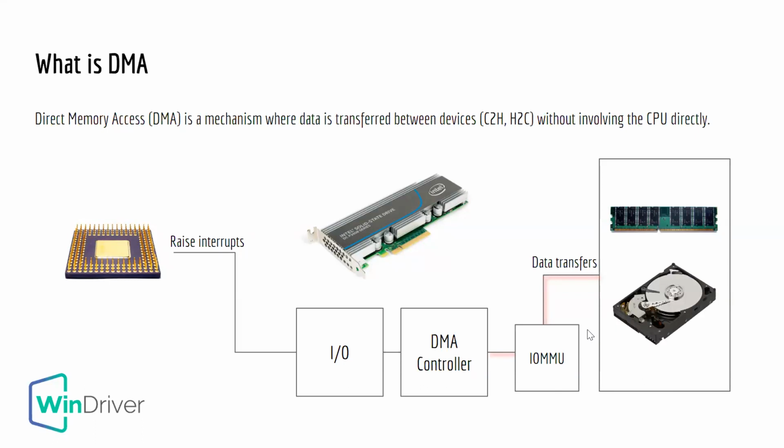Now, you may think intuitively that it shouldn't change the speed or should not enhance it because the DMA controller should do that best. However, we found that enabling the IOMMU can end with higher or faster DMA performance. I will show it in a few moments. So in essence, the DMA facilitates rapid data transfer while IOMMU ensures secure and controlled access to memory during DMA operations. They work in tandem to optimize system performance and maintain data integrity.